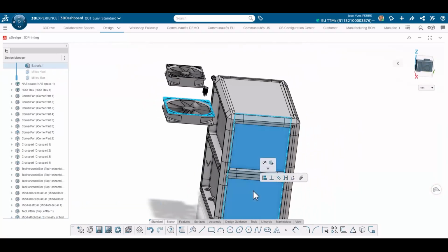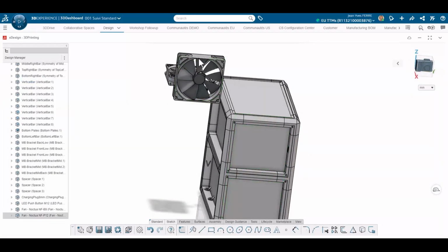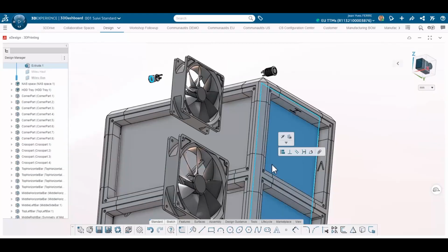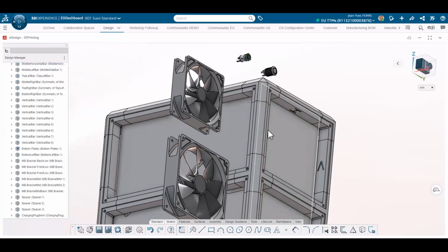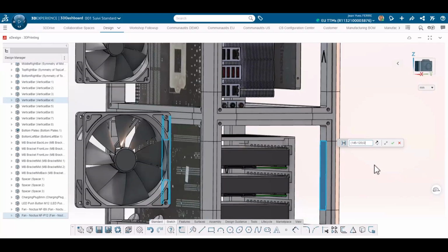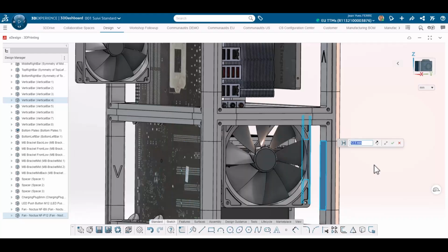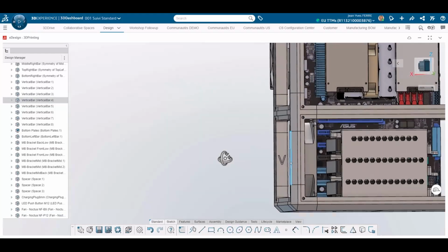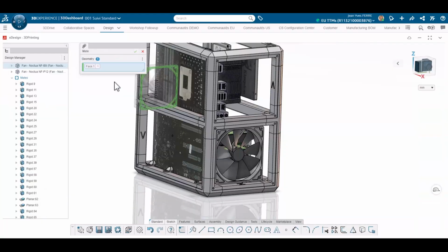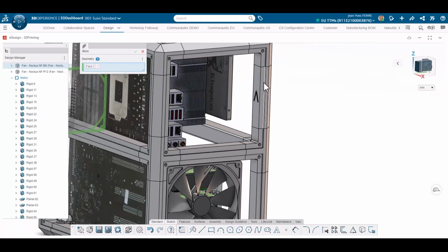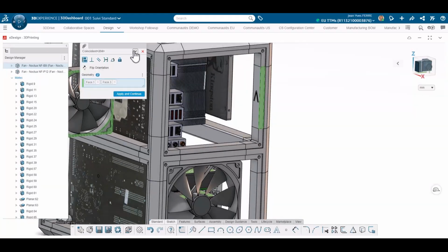First, I measure the available space to place the bottom fan right in the middle. For reference, I use the box I defined earlier as the computer's internal space. Now here's where things get tricky. You might already guess this isn't the ideal approach. The box I used isn't aligned with the planar face we need for the back panels. Yet I went ahead and positioned all the components on this incorrect plane. A solid start, right? Once I position the bottom fan horizontally, I understand I need to update the fan mates.